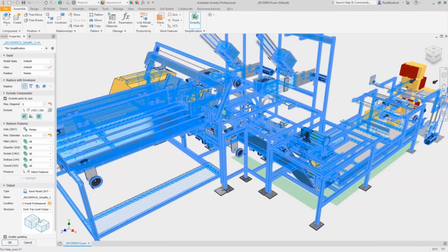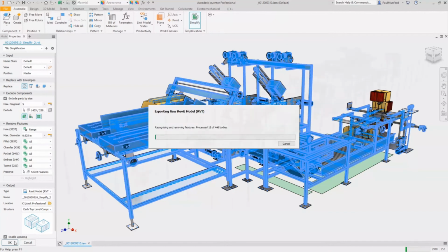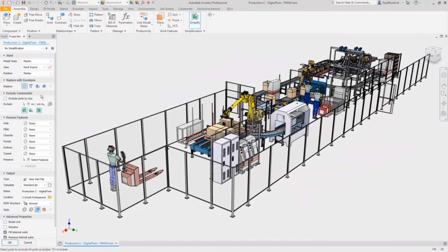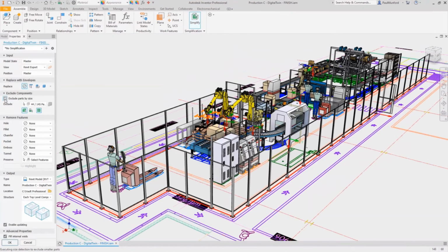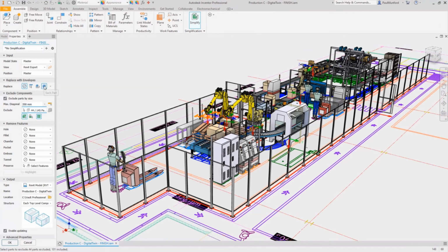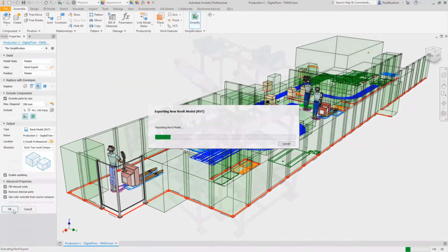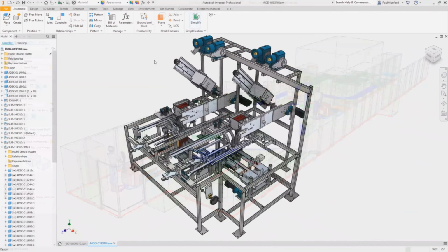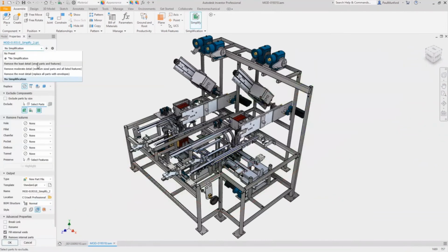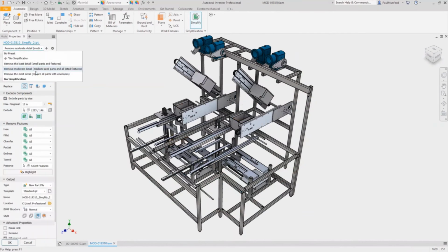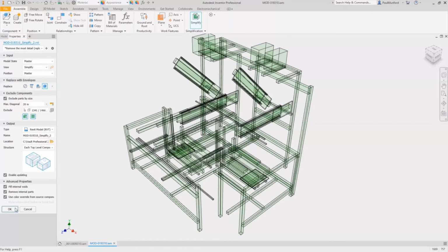By setting the output type to a Revit project or RVT file, additional settings are revealed which allow us to structure our output. Each top-level component option allows us to export a model in which the top-level Inventor assembly can be scheduled and tagged inside Revit to completely strip your manufacturing model of all detail and envelopes. This can automatically be added, which can replace components or sub-assemblies with a bounding box to simplify that down further. So quite a lot of preset options there with regard to that.